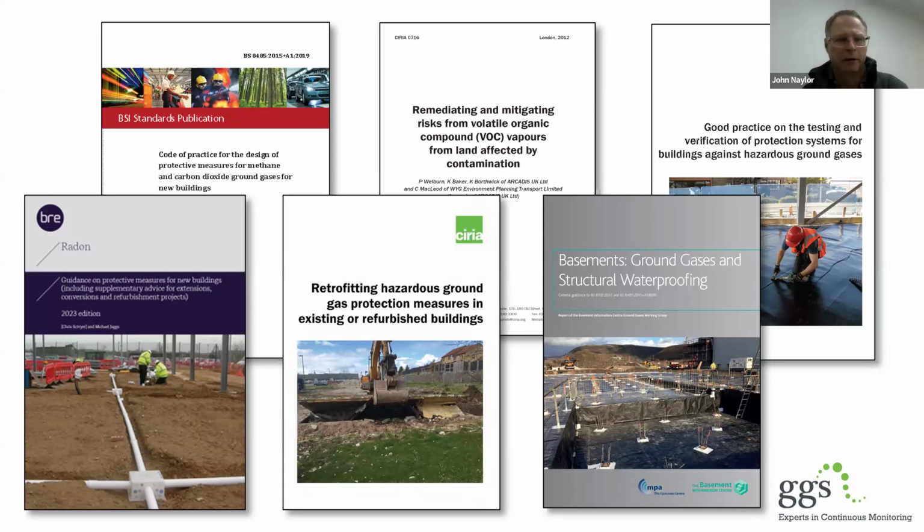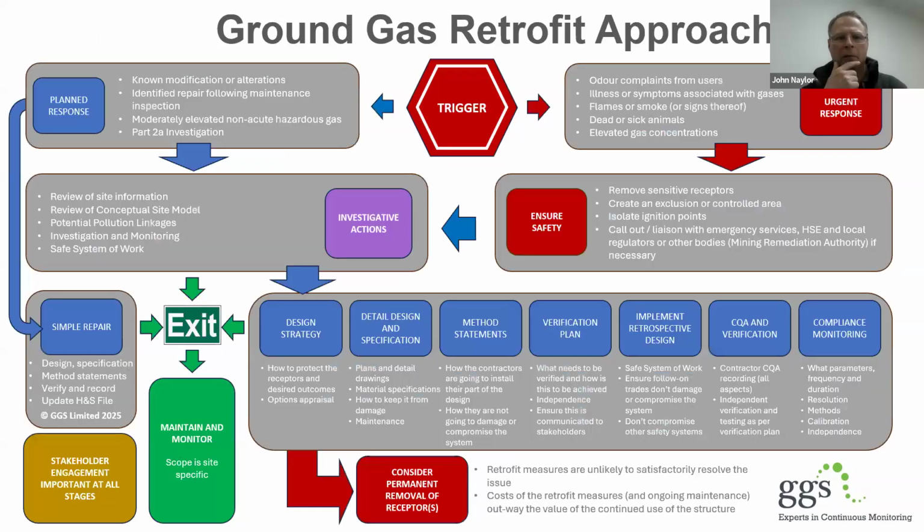But the British Standard 8485 we've got there. We've got the BRE 211, which talks about radon. And then also basements, ground gases and structural waterproofing. There's a document there from the Basement Information Centre that talks about ground gas protection in those scenarios. So there are things out there that we can go and look at, go and read, go and learn. So please do grab copies of those if you haven't already. But just to show you what the process is, I've come up with this sort of flow chart.